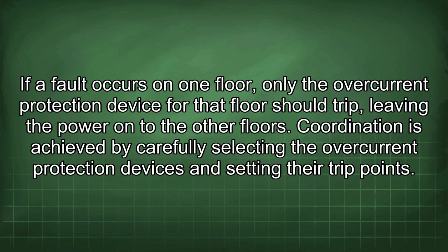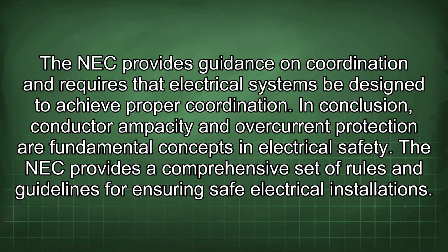If a fault occurs on one floor, only the overcurrent protection device for that floor should trip, leaving the power on to the other floors. Coordination is achieved by carefully selecting the overcurrent protection devices and setting their trip points. The NEC provides guidance on coordination and requires that electrical systems be designed to achieve proper coordination.